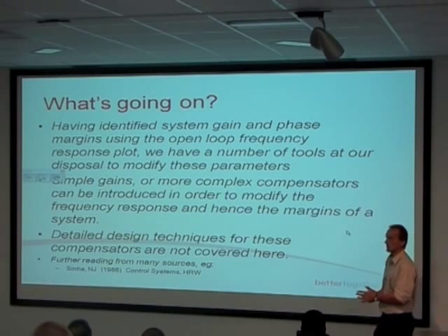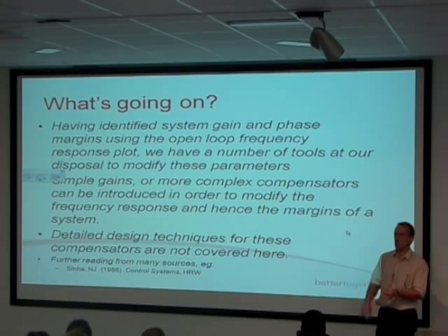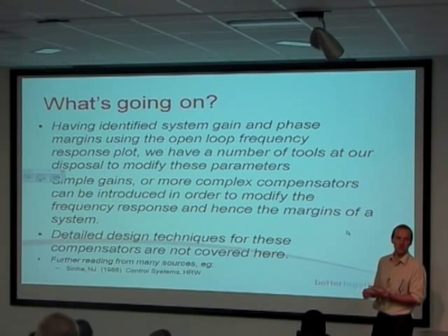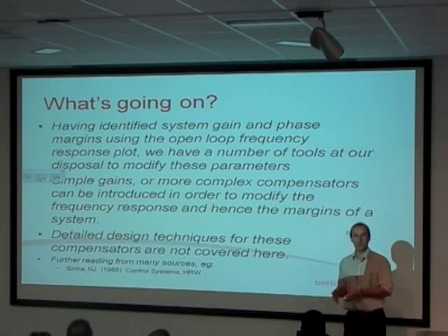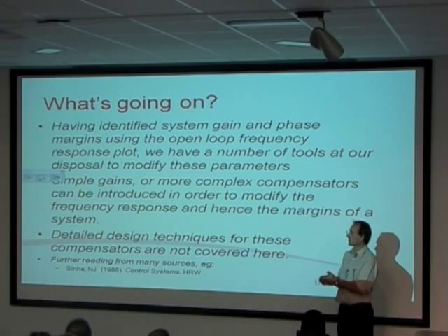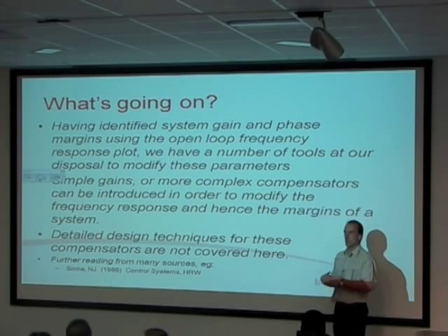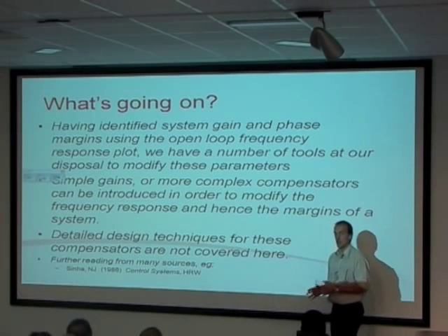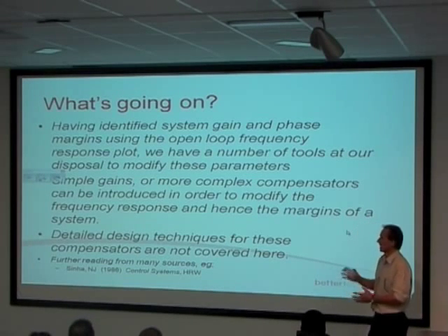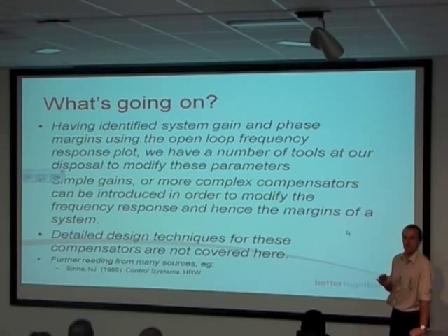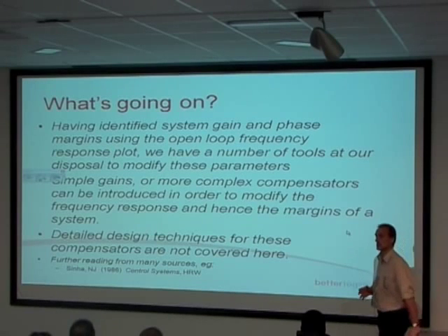So we introduce these more complex compensator patterns. Lead compensators, lag compensators, and then ones that are a combination of the two, lag-lead and lead-lag. What we can do with those is some more specialist modification of that frequency response plot, typically by looking at what's happening in a phase plot and moving things up or down to suit ourselves. As I say, in this module we don't have time, unfortunately, to cover the detailed design techniques for these, but you will find it in any decent control text.